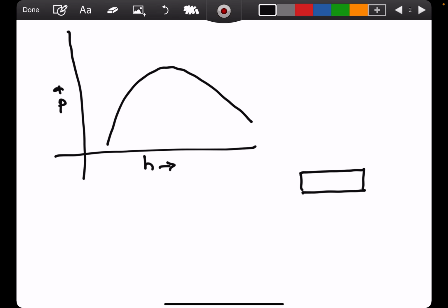One is for heat rejection, and one is for giving you the refrigerating effect. The heat exchanger which gives you the refrigerating effect is the evaporator, and the heat exchanger which rejects the heat is called a cooler. This is not a condenser, mind well. This is a cooler because you are talking about the region above the critical point. So one is the evaporator, the other is the cooler.